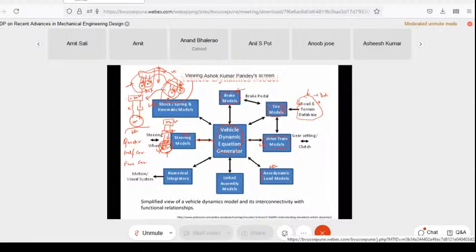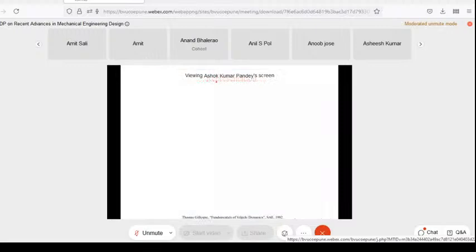Now, the one thing that we need to really understand is how to represent a vehicle. Many people forget to know how to represent a vehicle properly. So first of all, one can see whether you are going for a one mass approximation of the vehicle. If it is just longitudinal motion that you are trying to deal with, where the tire influences are not really required, we can just take a one mass approximation, where we are doing some acceleration analysis, cornering analysis, right? But when we do comfort analysis, then we need to go for two masses or higher masses approximation. Okay. So how do we do it?